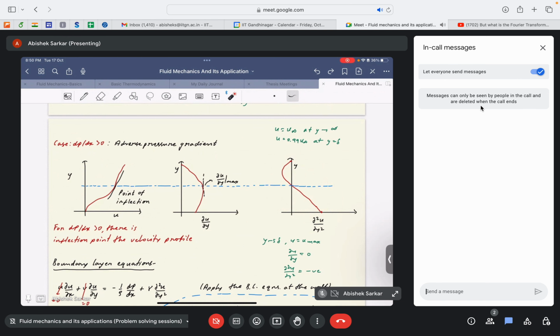See, it might also happen, which usually happens in the case of flow over curved surfaces, that since a pressure gradient exists over the surface, the flow would usually accelerate within the boundary layer or within a certain region. Wherever there is a favorable pressure gradient, the flow would accelerate at that point, then reach a maximum value, and then consequently diminish to the free stream value.